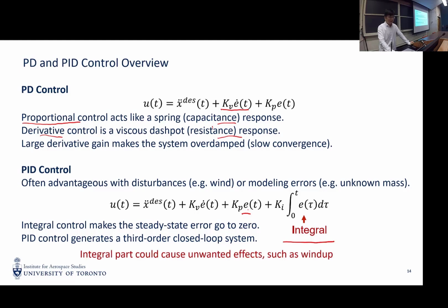But if you choose to use integral control, you must be aware of some undesired effects such as wind up. It means saturation of your control input. If the external disturbance is too large, it may cause a saturation in your input, and it will degrade your dynamic performance.